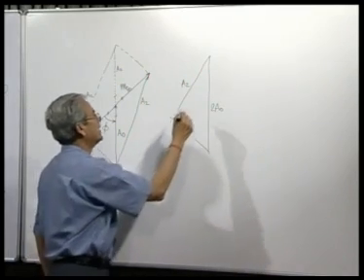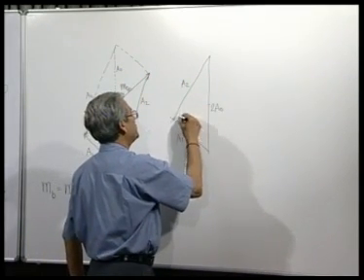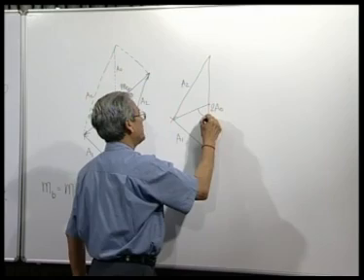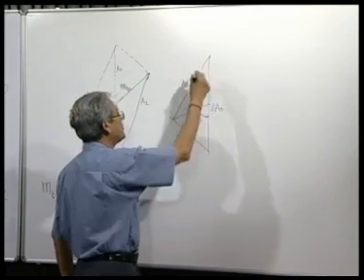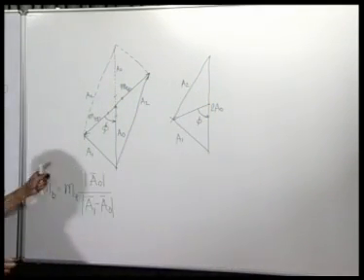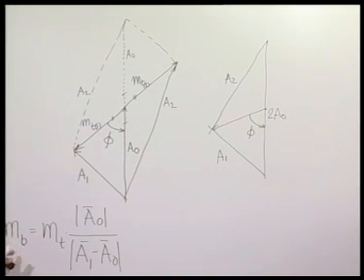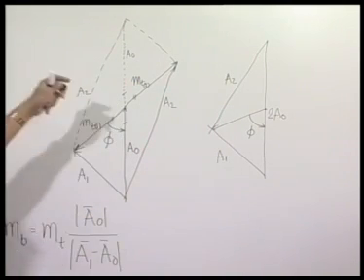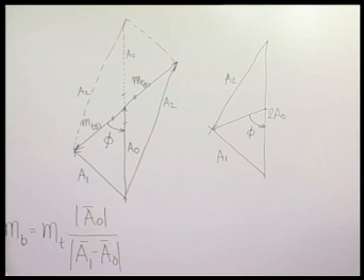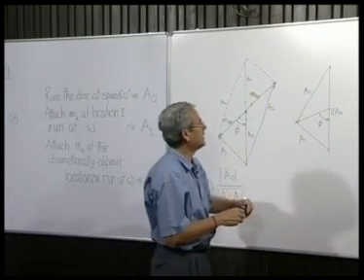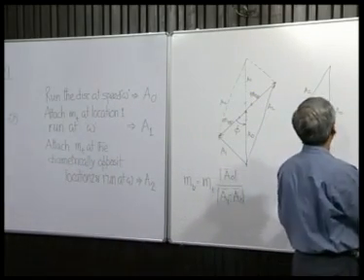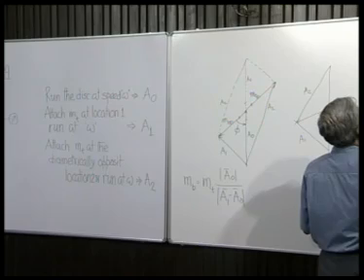The moment we do that, the midpoint if we join, this becomes phi. So, phi is known from this diagram, and the magnitude of the balancing mass required to neutralize the effect of the original unbalance we get here. This is okay, but there is only one snag, that when I draw a triangle like this, I can draw the triangle like this also.